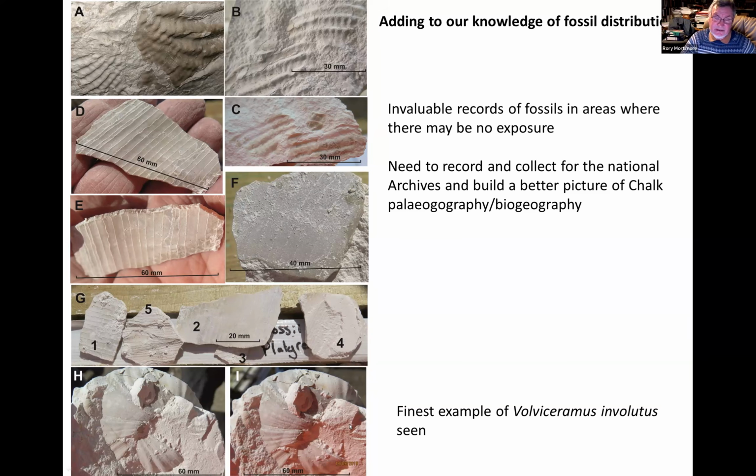This happens to be on the A303 Stonehenge boreholes. And these here are Dover tunnels and places of a different type of inoceramid. This one has a wonderful name, Cladoceramus undulatum, and this one is Volviceramus. They're completely different, but one occurs above the other, so you know where you are in the succession. As soon as you find these, you're confirming where you are in the chalk succession.